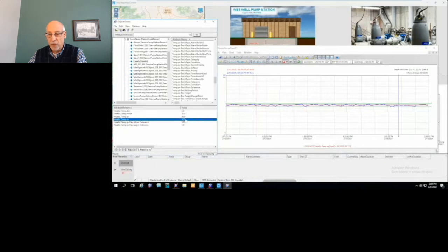And then also you can see on my process chart here, you can see when I change the set point, and you can see the process variable is now tracking. Right, so that's a nice feature with our trending control, that we're tracking when operators do things on the actual trends themselves. So great tool, this simulator I'm using here, to be able to track the process variable. Looks like it had a pretty nice PID loop here, so it tracked pretty quickly, and it's still in control, right? So it's not out of control at all. It's still within the alarm band condition. So everything's looking good here.